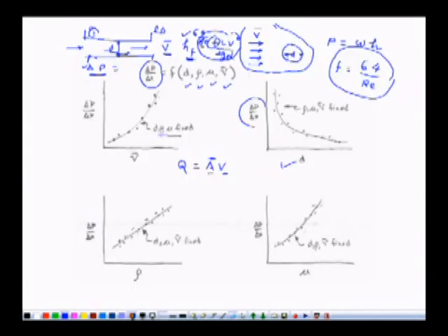So, we have to conduct another experiment. For that, we need to measure del P over del X, which can be measured very easily in the lab, but we need to change the diameter of the pipe. So, we must have a large number of pipes having different diameters and conduct this experiment keeping other parameters fixed, like rho, viscosity and velocity constant, and then we can say that corresponding to this diameter of the pipe, this is del P over del X. We can find it out, right.